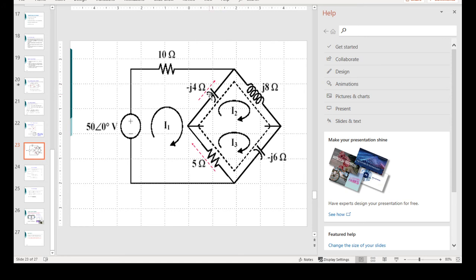Now the only thing which we need to note, as I have said, is the currents that are flowing there, right, and here. The red arrows that I've put indicate the current I2 and I3. So when you come to do the KVL equation for this super mesh, there is no source, so it's 0 equals to.